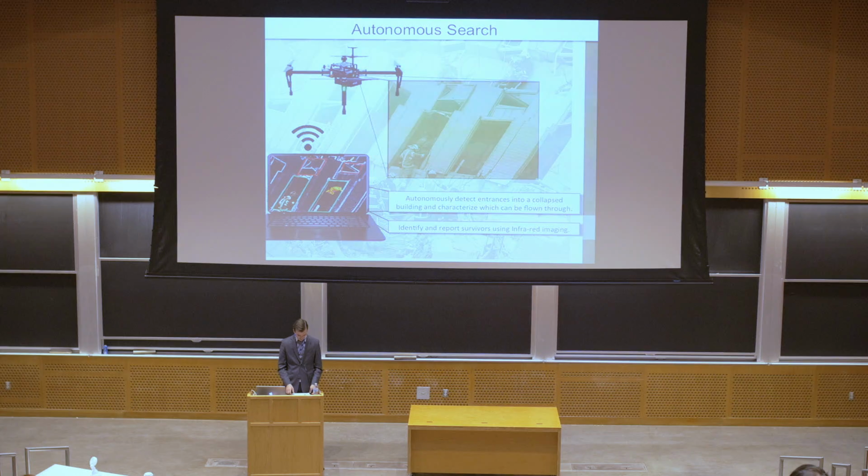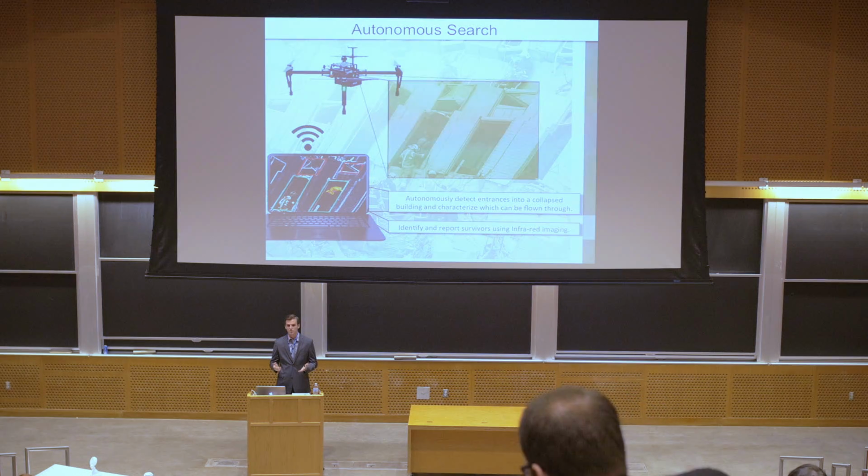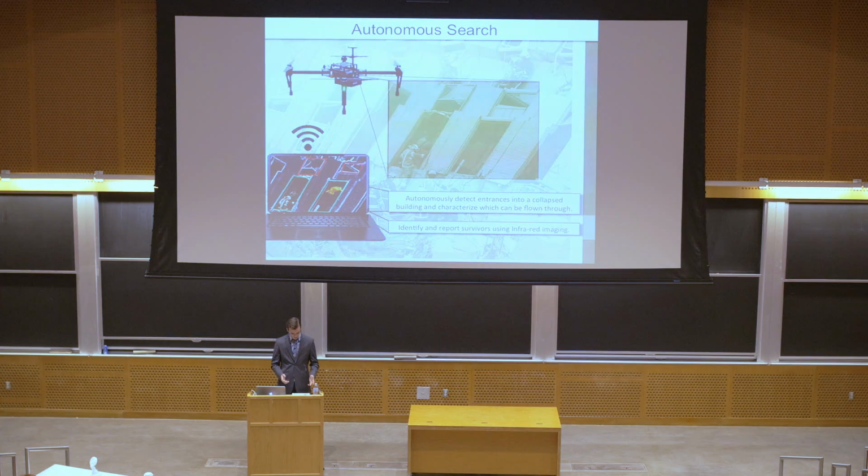The UAS is also equipped with 10 low-resolution cameras that serve in pairs to accomplish stereoscopic imaging for collision avoidance. This system serves essentially as a safety net that overrides flight control to avoid obstacles and prevent collisions while both the thermal and autonomous navigation algorithms are running.